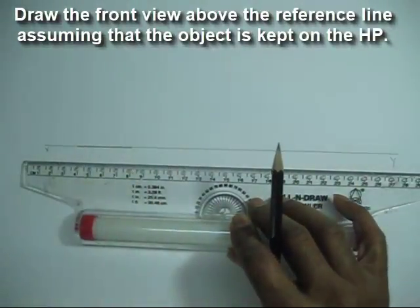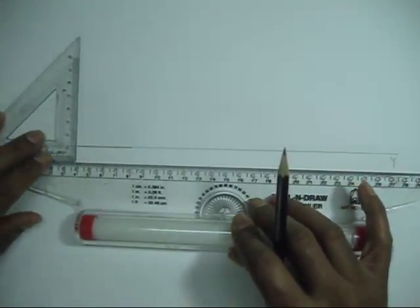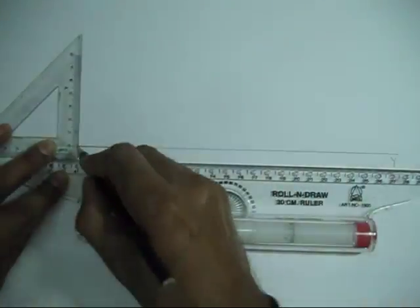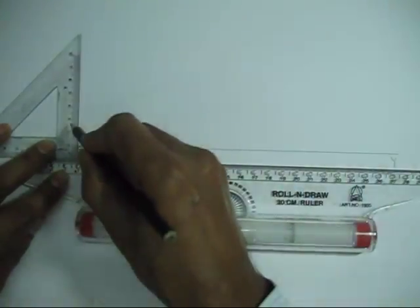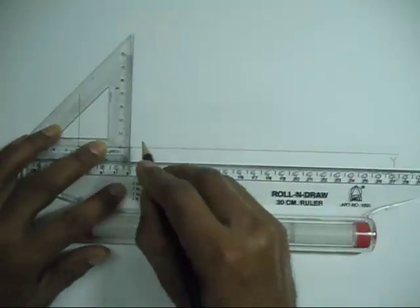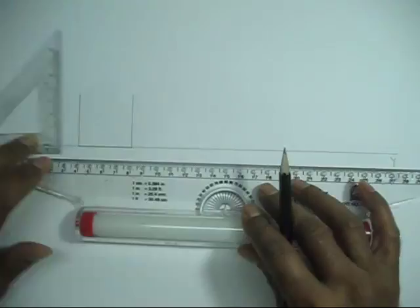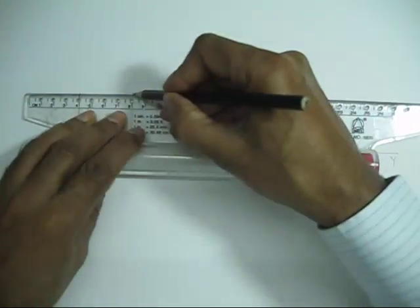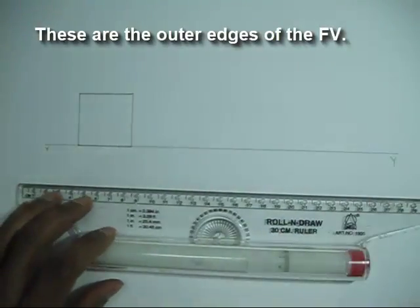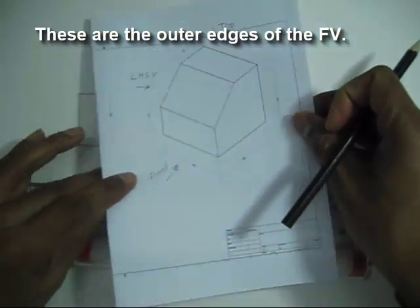Because this is in the first angle projection system, and we assume that the object is kept on the HP. So the side of the cube is 40 mm. So these are the outer edges of the front view.